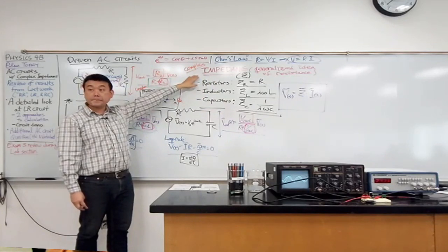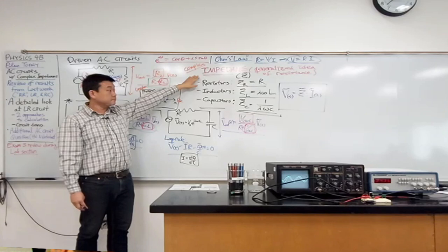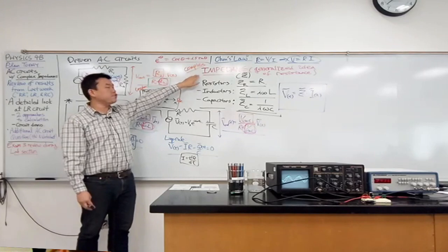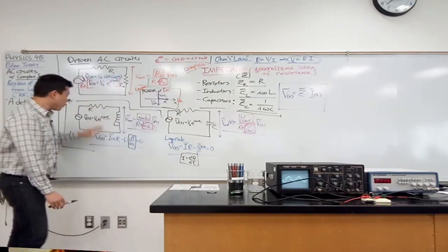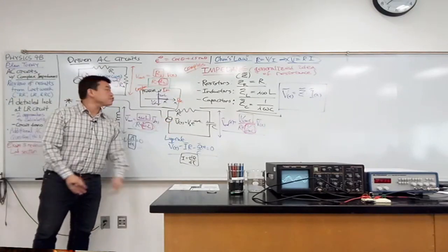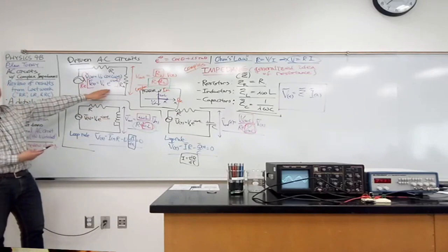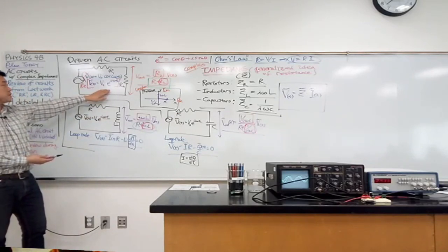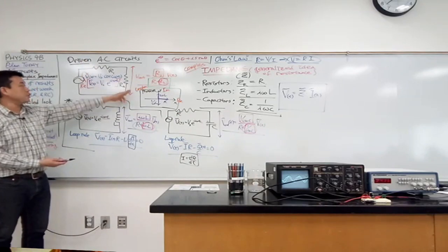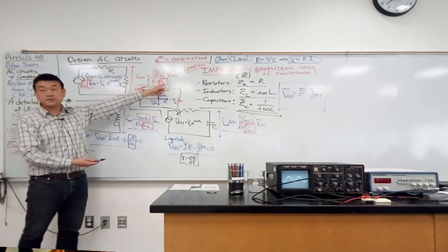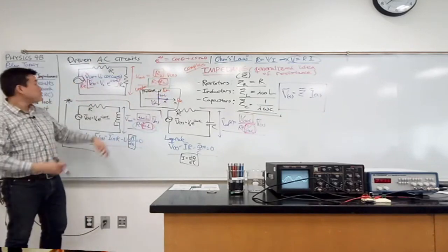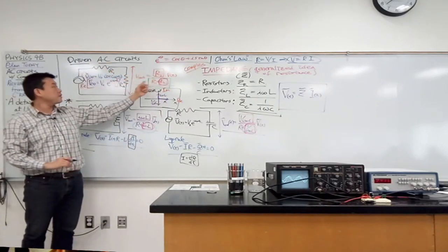Yeah? The idea is that this voltage gets plugged into the Kirchhoff rule? No, I mean, really what we are trying to do in introducing impedance is that I don't want to go through Kirchhoff's rules again. Because you remember how simple it was to solve this question. You didn't have to go through Kirchhoff's rules. You could just simplify this as an equivalent resistor, R1 plus R2, get the current, voltage over R1 plus R2, multiply by resistor R2, get the voltage out.